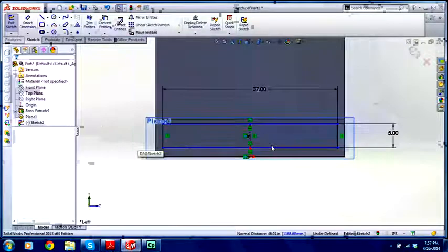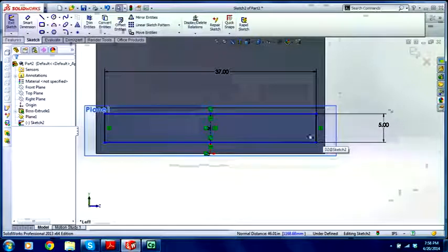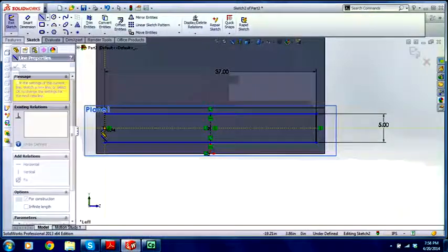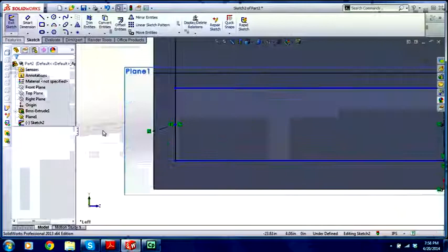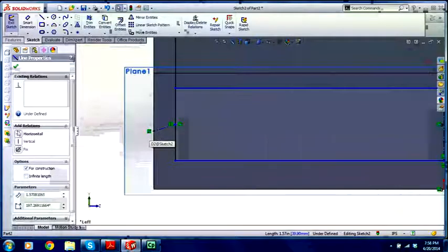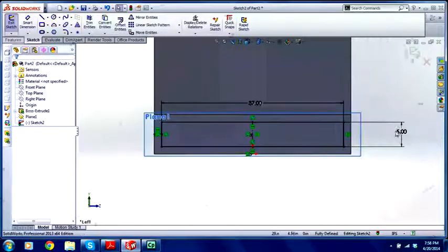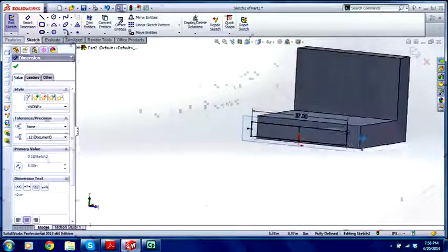And then what else can I do if I want to have this? What's the quickest way? I know that that's 8. I can go from that center to that center and then just make that horizontal, and it'll bring it down. A couple of different ways of doing that. So it just keeps that rectangle centered on that rectangle.